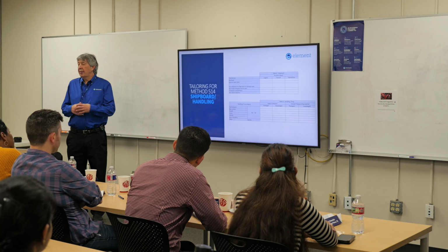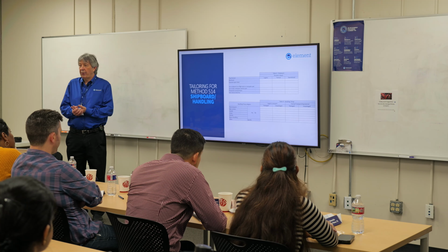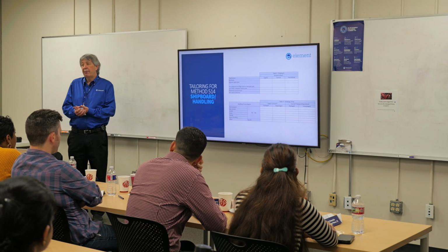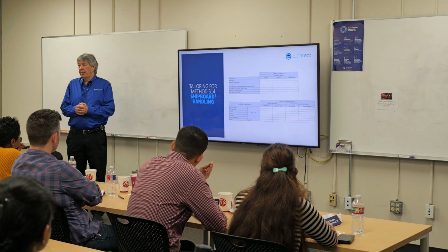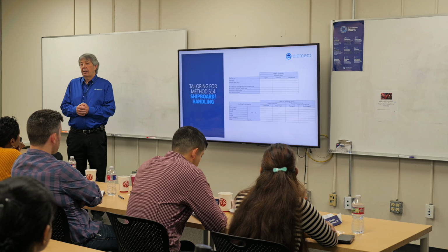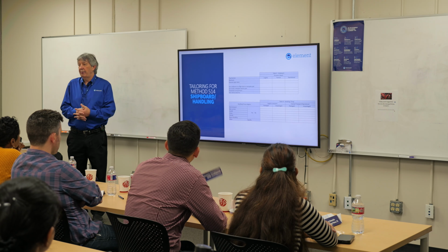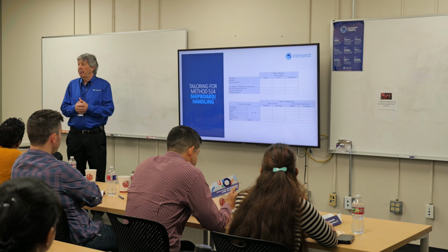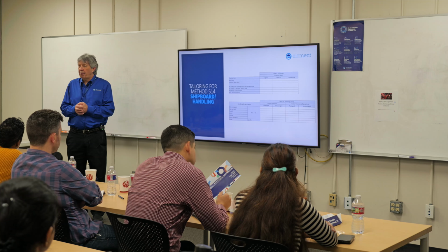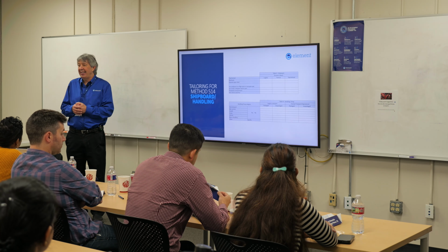So in MIL standard 810, we're not talking about it, but we'll give it a quick second. Method 528 is shipboard vibration. It's actually a rewrite of MIL standard 167. The Navy doesn't like you to reference MIL standard 810 method 528, even though it's exactly the same. They like to see MIL standard 167-1. So when I talk shipboard, just remember it should be 167-1, not method 528.